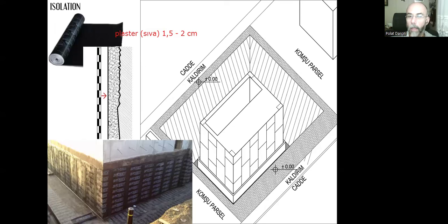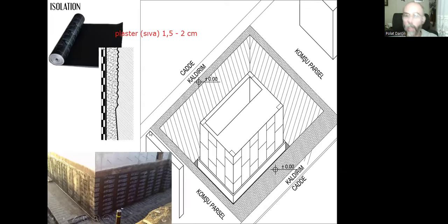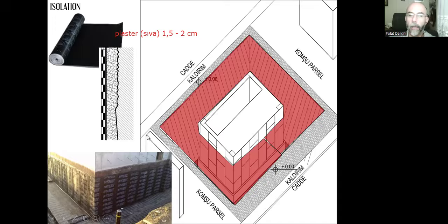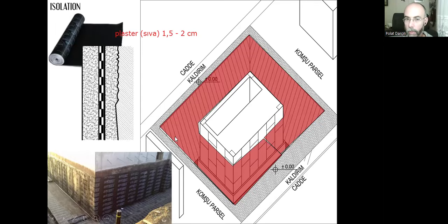We can apply the liquid base, and over that we can apply our two bitumen sheets. And when we place the earth back, there can be sharp particles, sharp gravel inside the earth. Again, it can harm our membranes, so we need protection. Also, we need heat insulation as well, because as you remember, there will be a basement floor. The basement floor will be heated, and there can be heat transfer through the earth between the outside air and our basement floor, so we need heat protection.